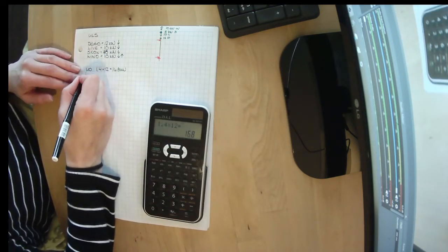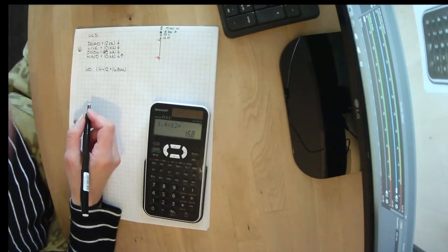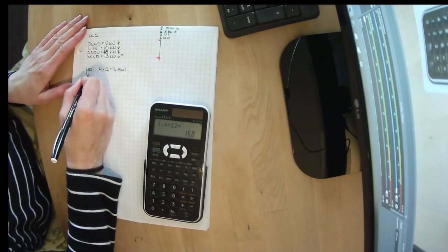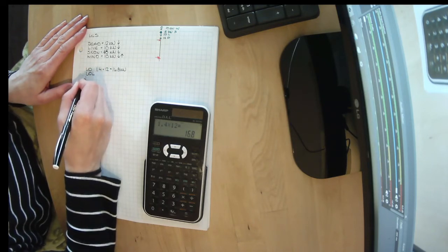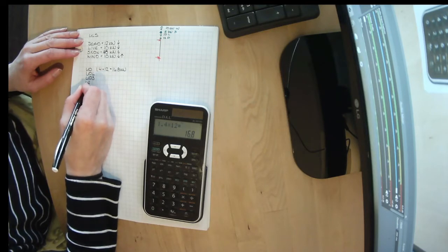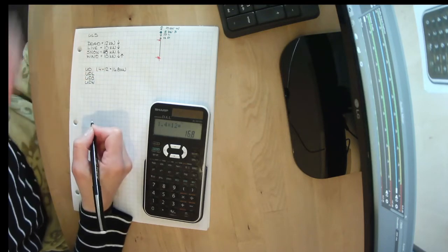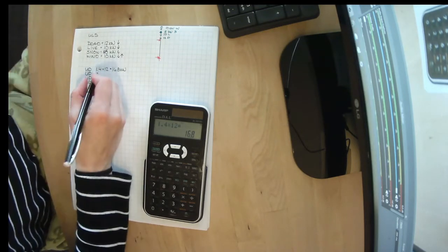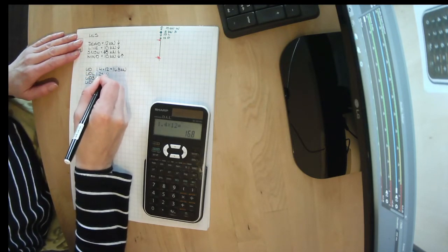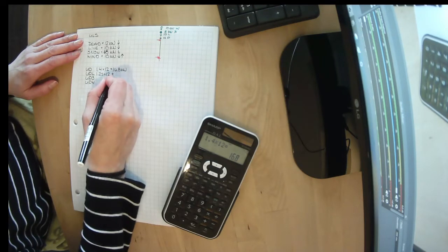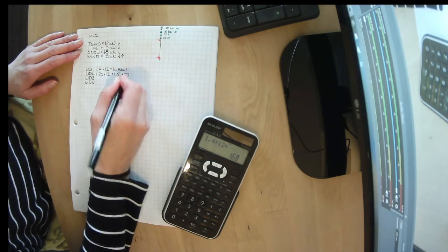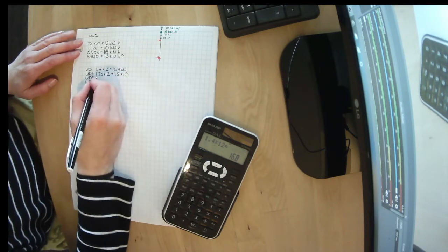So we know that there can be dead and the principal loads. So we could have dead and live, or dead and snow, or dead and wind acting downwards. And for that, we knew that it could be 1.25 times our dead load plus 1.5 times our live load.